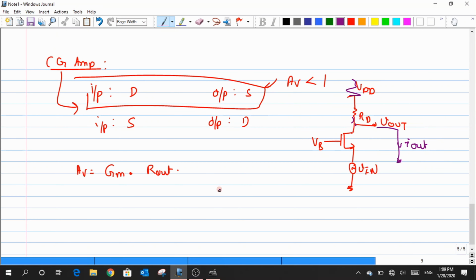So basically the gate potential is a DC, due to which I connect it to ground, and the source is already connected to my Vin. So I retain this value of Vin just because when I try to compute the Gm, what I do is that I fix my Vin. Okay. So now based on this polarity that I have defined for this VGS, I first define the current direction that flows between the drain and the source. Okay, which is gm VGS, and I also have this ro.